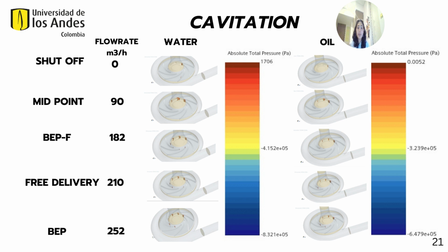The information above means that the pump is poorly designed. This is confirmed by talking about cavitation, because it is observed that there are points near the center of the impeller that cavitate. Those are the internal parts of the plate. Taking into account that at these points the absolute pressure is less than the vapor pressure of the fluid, creating a negative suction that tends to damage the pump, because cavitation allows the fluid to boil and create bubbles that affect negatively the pump. This cavitation is minimal. However, since it is present, it reduces the efficiency and effectiveness of the pump. Ideally, the pump should not cavitate, indicating a good design.